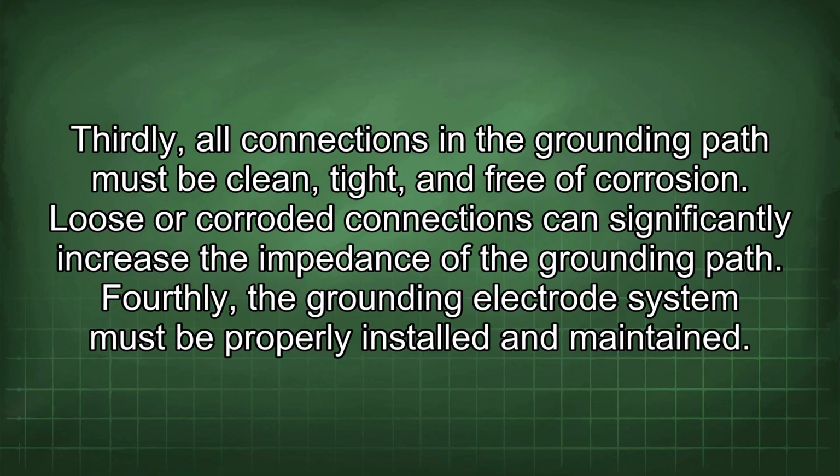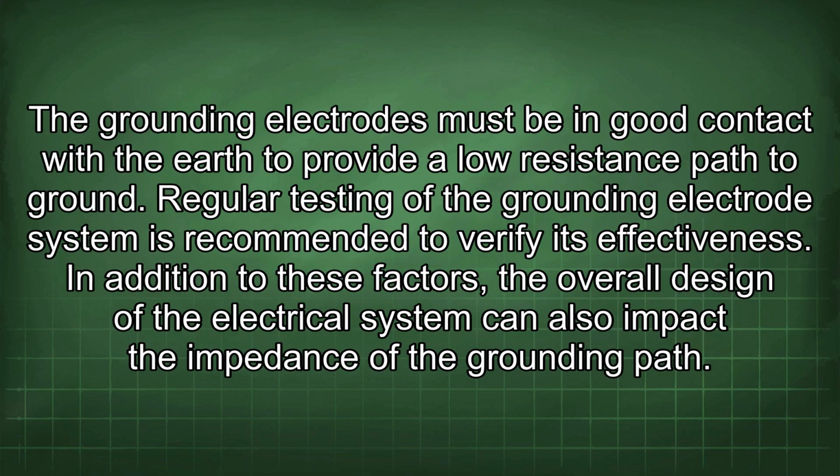Fourthly, the grounding electrode system must be properly installed and maintained. The grounding electrodes must be in good contact with the earth to provide a low resistance path to ground. Regular testing of the grounding electrode system is recommended to verify its effectiveness.